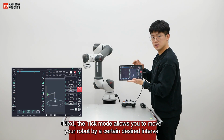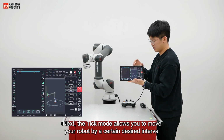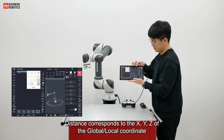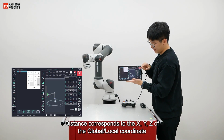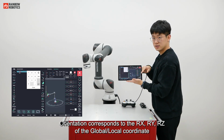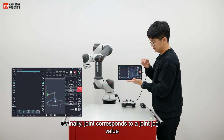Next, the tick mode allows you to move your robot by a certain desired interval. Here, we have distance, orientation, joint. Distance corresponds to the X, Y, Z of the global or local coordinate. Orientation corresponds to the Rx, Ry, Rz of the global or local coordinate. Finally, joint corresponds to a joint jog value.